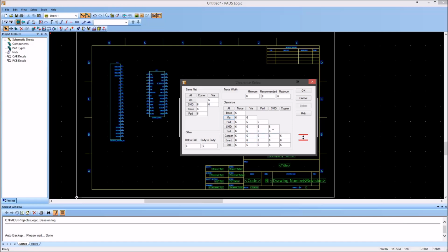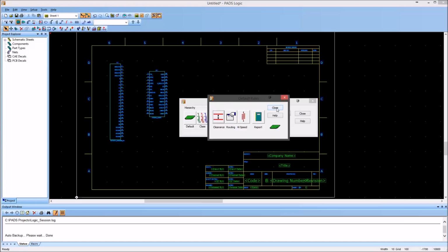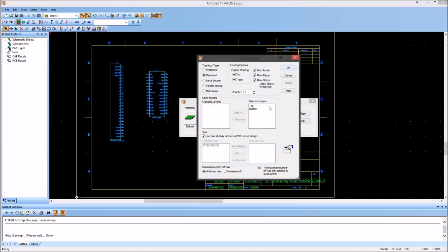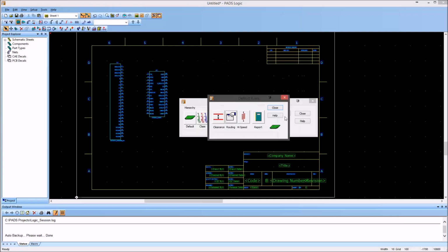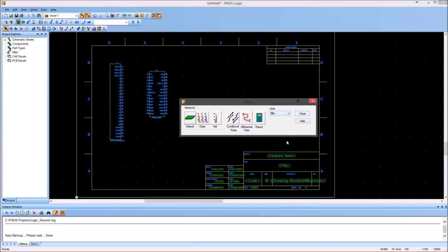And doing it at the end is okay if you forget, but chances are you're going to want to start with this. That way you don't have to go modify all kinds of your board layout to get it to work properly. You can also later choose priorities for how different nets or pins or all kinds of stuff are routed so that they're prioritized, but that's not going to be till later.